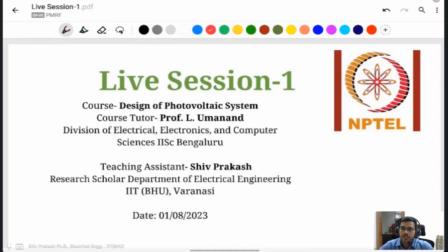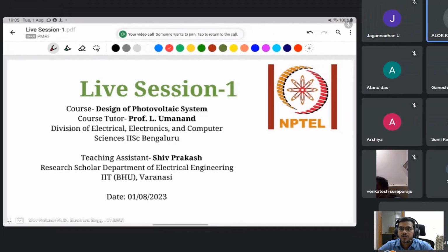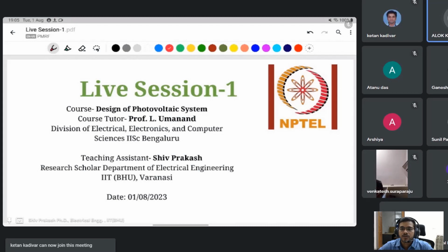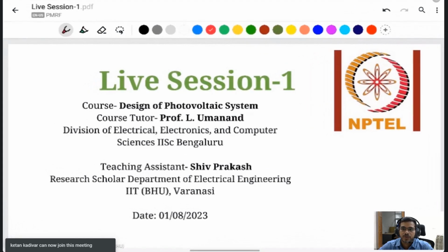Good evening, sir. Sir, I have a doubt. During the lecture, sir told the load line concept for two similar solar modules. But my question is, what will happen if we connect two dissimilar solar modules, like one of 50 watt and the other of 80 watt? What will be the effect on the load line, and why do we always connect two similar modules in series or in parallel, not two different ratings?